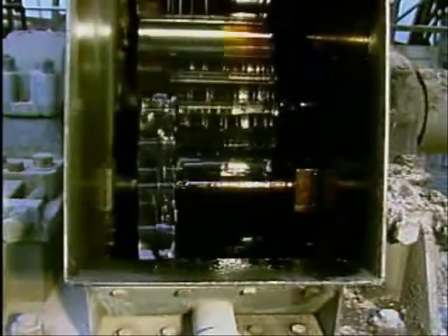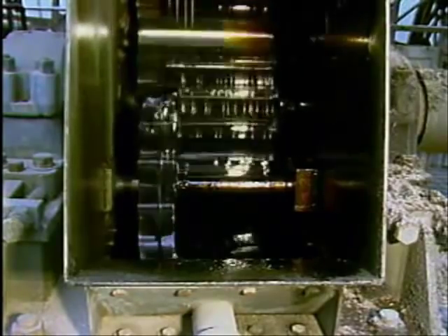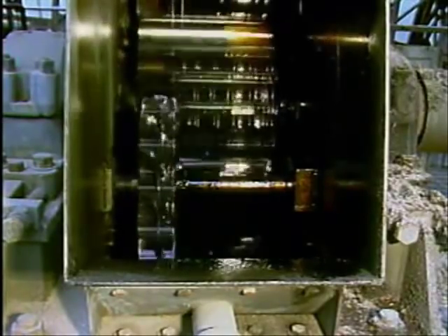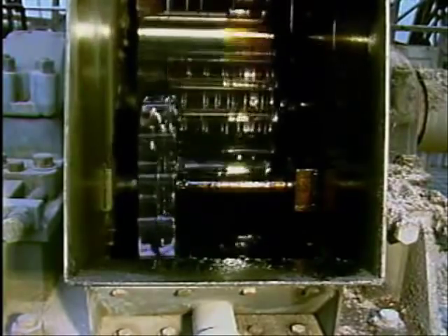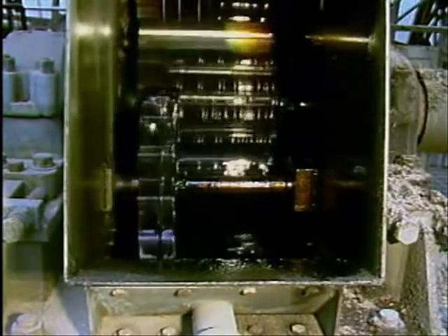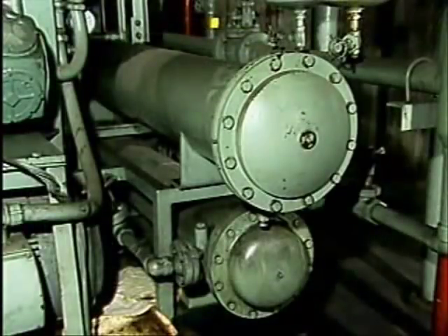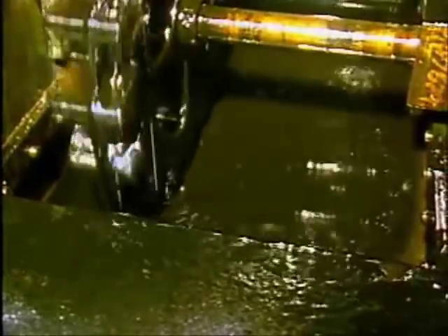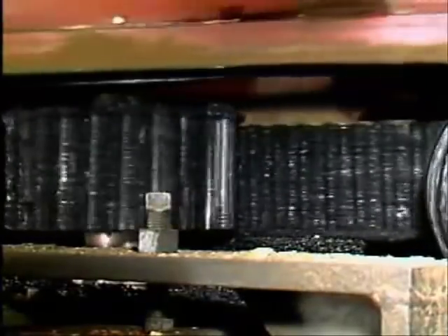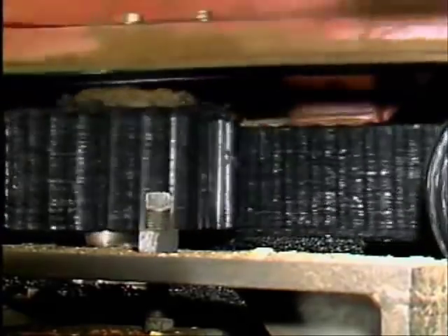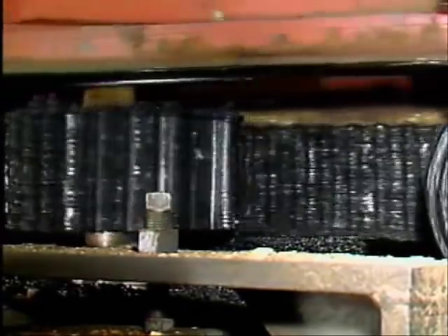Heat can cause problems for gears when a lubricant does not remove the heat quickly enough. Heat damage can cause gears and gearboxes to distort, which can result in severe misalignment and damage. Overheating could be caused by a loss of cooling water flow to an oil cooler. Temperature may also become a problem if it's too low. If the temperature is too low, lubricant flow may become restricted, which robs the gearbox of its lubrication. Another lubricant condition that can cause gear problems occurs when lubricants become contaminated with dirt, sand, metal particles, sludge, or acids.